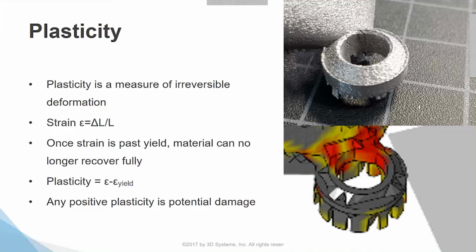And when I say potential damage, it should be noted that all of these parts will basically always have some form of plastic damage, and it's usually unnoticeable if it's just surface damage and a little bit of curling. It's still damaged, but it's absorbed during the printing process. It can be absorbed in that layer height and remelted, but it's still there. Don't want to ignore it.